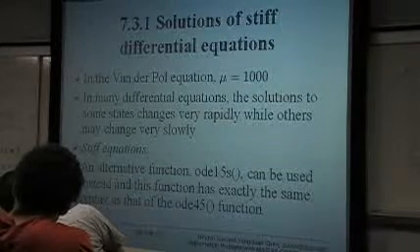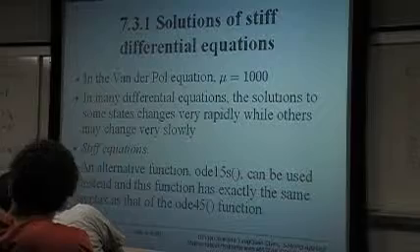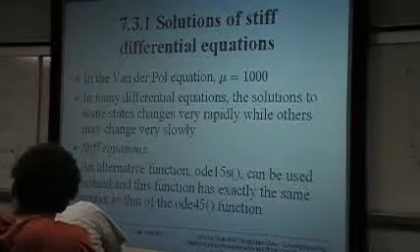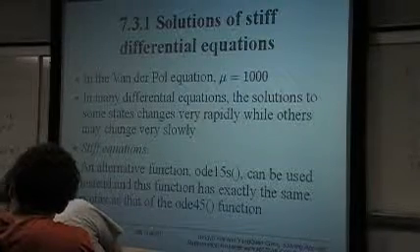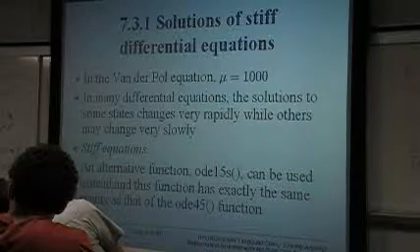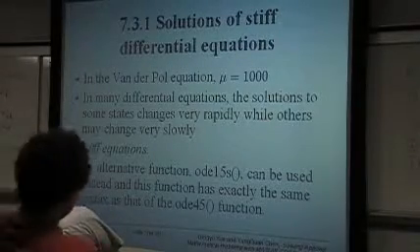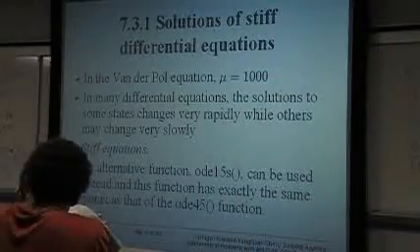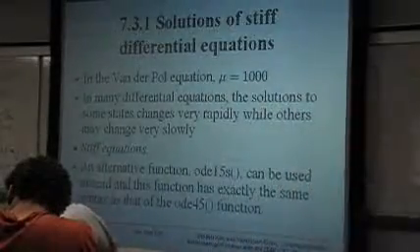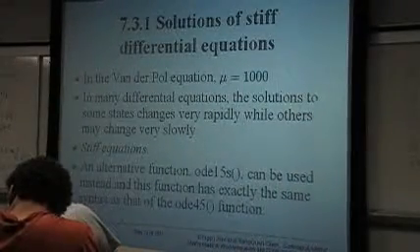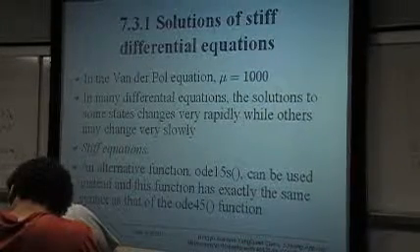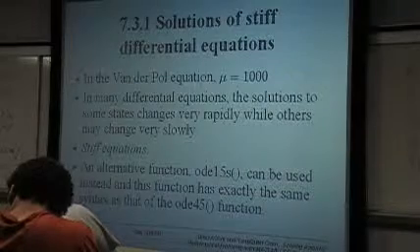So what you need to do is to try to use ODE45 first, and if for quite a long period of time you do not find any solution, then you terminate the solution process and change the solver. I think this is the only feasible way to check whether an equation is stiff or not. There isn't any existing method to check it before solving it.